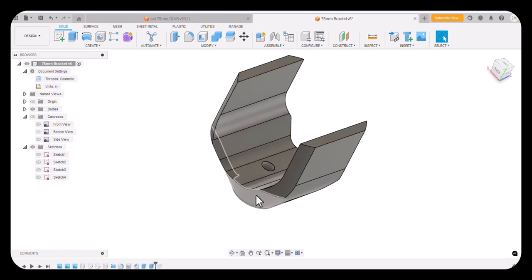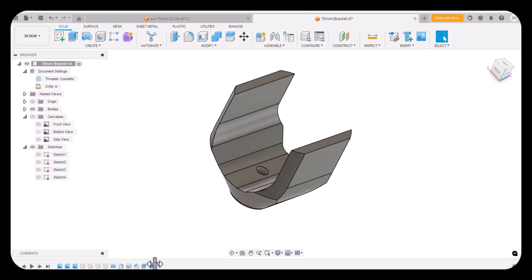And when we're doing our tooling, we need to make sure our fastener doesn't quite come up to that hole. We end up cutting our fastener, so it should be a little bit below the top of that hole. And as we're doing our milling, we might go ahead and put a chamfer in at this point, or we could do all the chamfers later. I think I'll do those chamfers later. And then I'm going to drill the hole next.